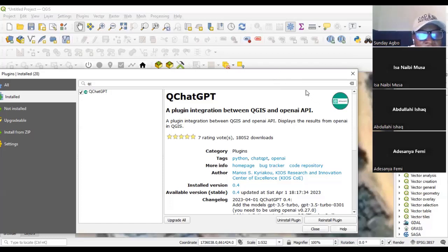Okay. Normally the way you add your layer, instead of selecting the one that is SHP, which is shapefile, you can select the one that is DWG. So your AutoCAD can come into the QGIS environment, but the only challenge is that it will not fall at the right position. It will not be georeferenced. All right. Okay. Any other question?